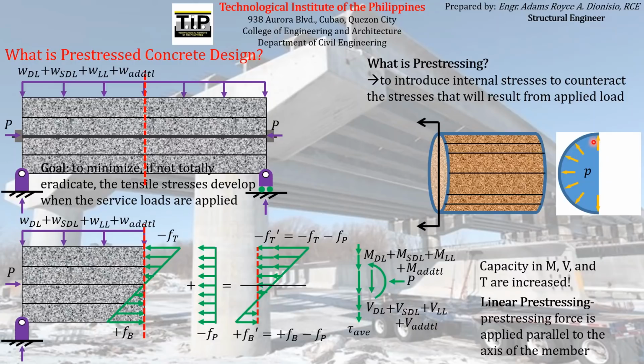So who will resist those horizontal components here? What will resist the horizontal components of the pressure exerted by this water on the wall of the tank is what we call the tangential stress acting on the wall of the tank or the barrel. If you can remember that tangential stress in mechanics of deformable bodies or fluid mechanics, that is the force that will resist the horizontal component of the pressure acting inside the barrel or the tank. And that is obviously a tensile force because it points away from the wall.